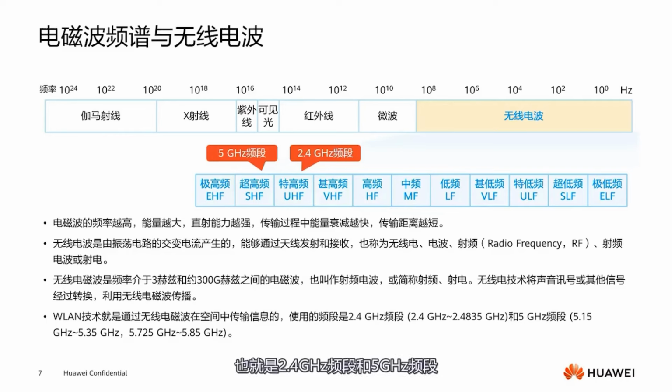It's important to understand that all these bands refer to a range of frequencies. It's not that ultra-high frequency is a specific frequency. Within this frequency range, I categorize it as ultra-high frequency. Within that range, I categorize it as extremely high frequency. Wi-Fi technology uses the 2.4 GHz frequency band. Its frequency range extends from 2.4 GHz to 2.4835 GHz. This place needs precision to 4 decimal places.